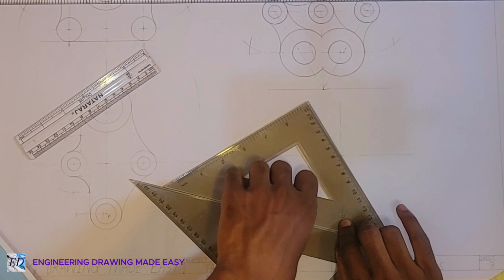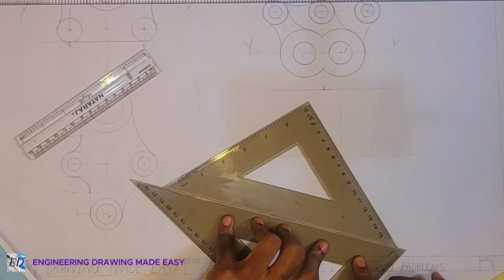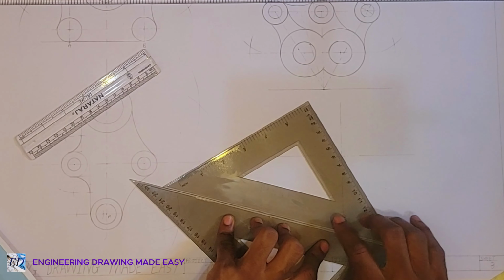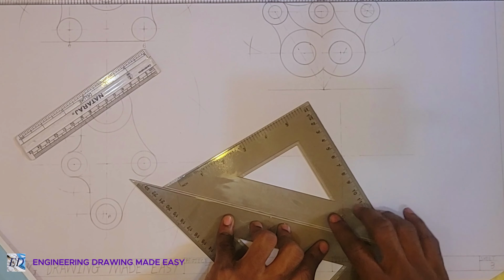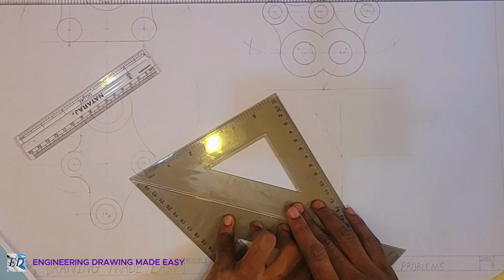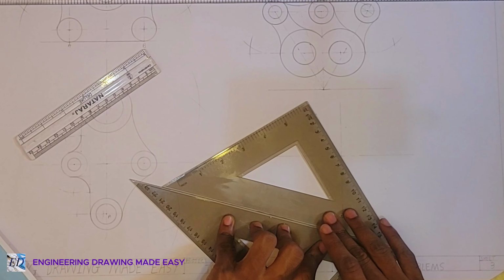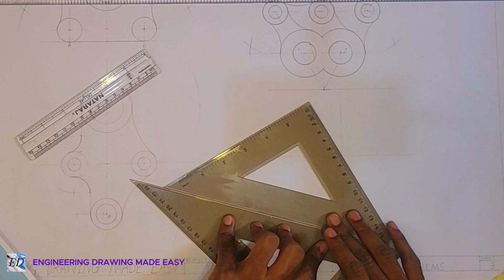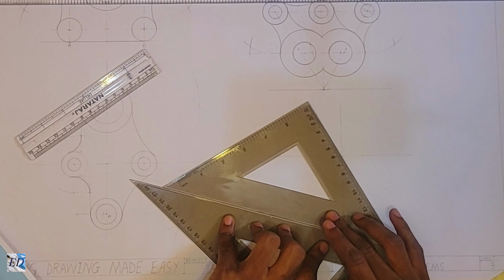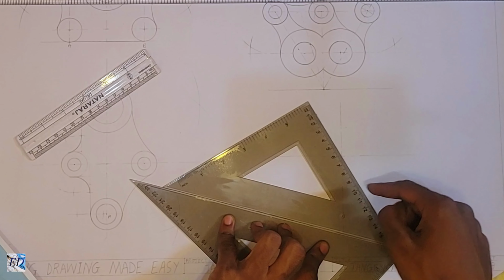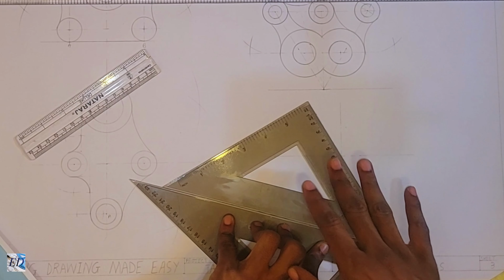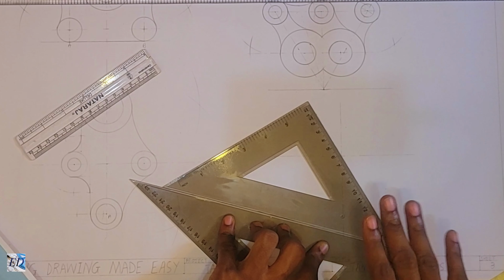Okay. So now that you have that, you keep the base one firm, right? The one at the base, you hold it down very firm, and then you slide the one on top of it. So when you slide, it should be able to come and meet the line again and fall exactly on it. It should fall such that you can trace over the line again against the edge of the set square. Okay, so this is really important.